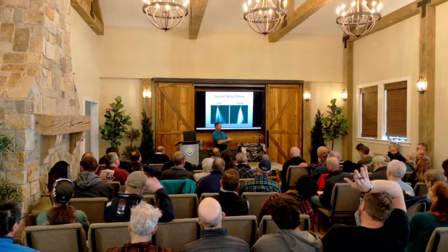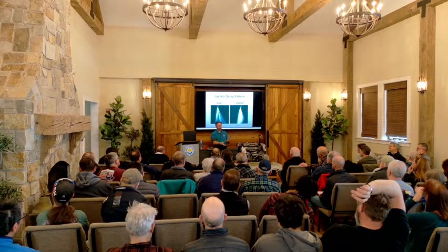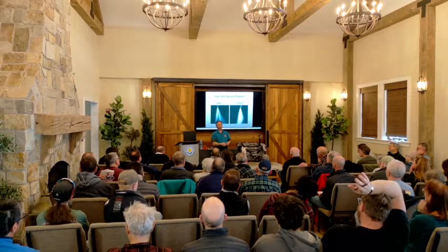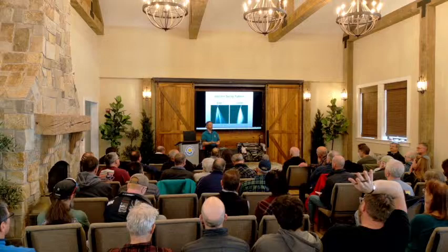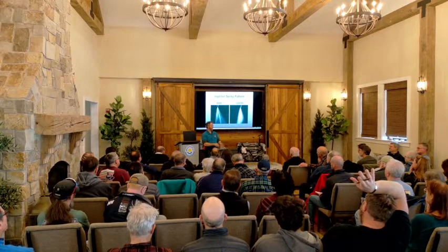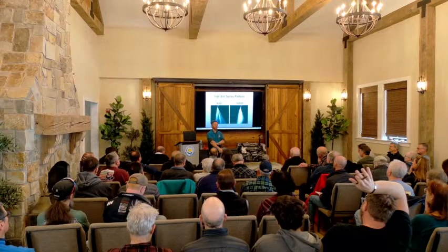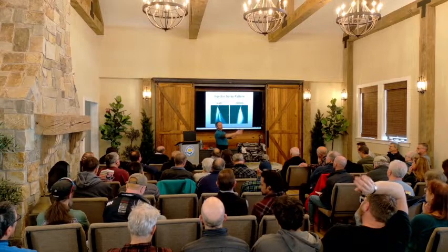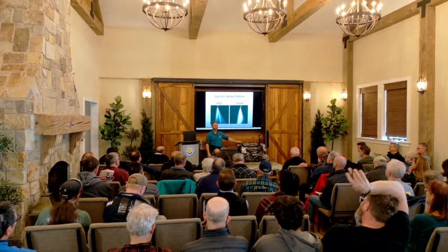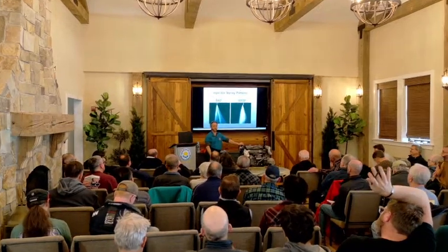Now, having the whitish gray smoke when the air is really super cold, it's not exactly a problem, it just doesn't look that great. What can you do about it? You can put a heater in your compartment, so it's starting off at a warmer temperature, and then once your engine is up to operating temperature, the compartment itself should be hot enough that it shouldn't affect the smoke coming out the back of the boat.